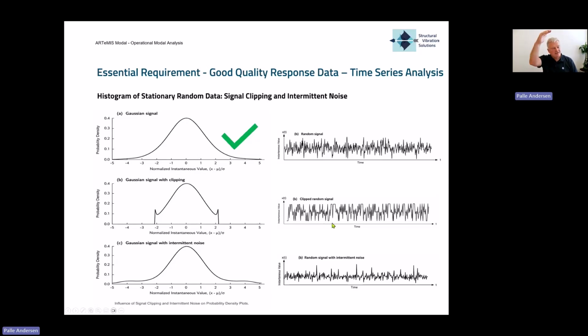You cannot exceed these two because the clipping prevents it from happening. So as long as we have data that is within the clipping region, it is nicely distributed like the top part of a Gaussian distribution. But the minute you get to the edge, it is cut, of course, at plus minus the clipping threshold.